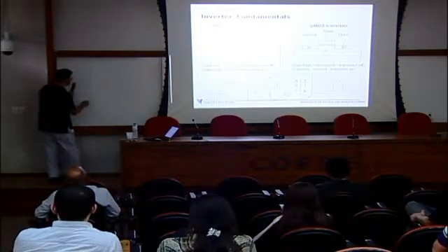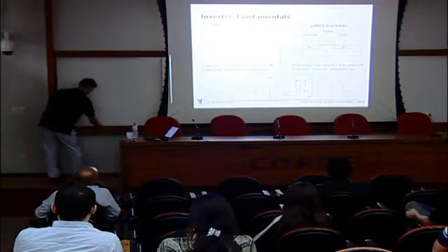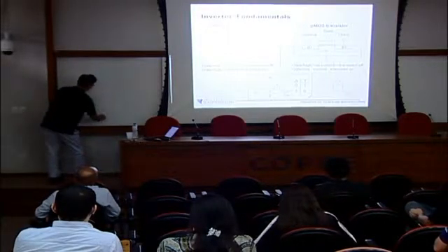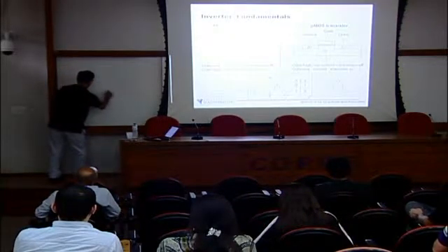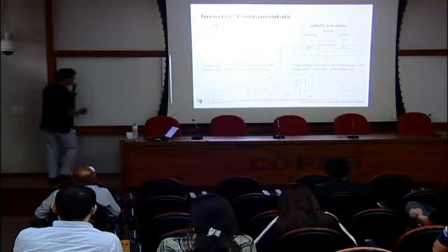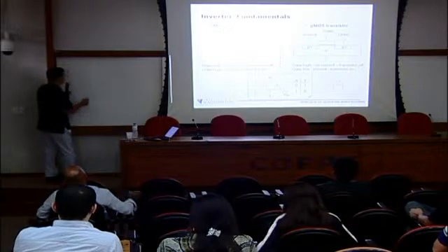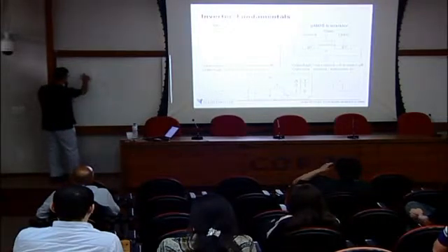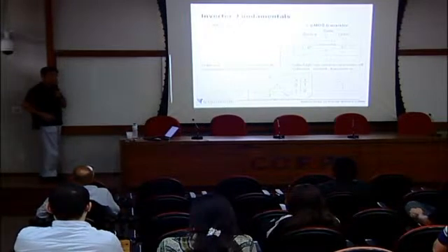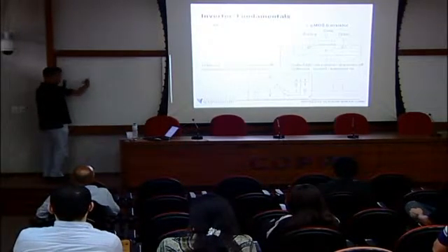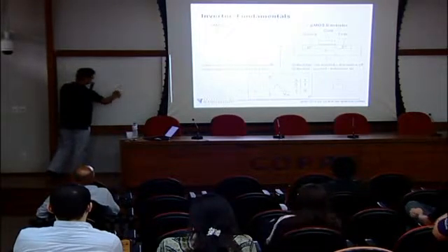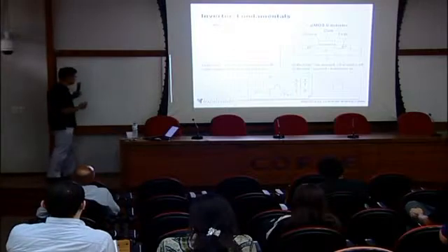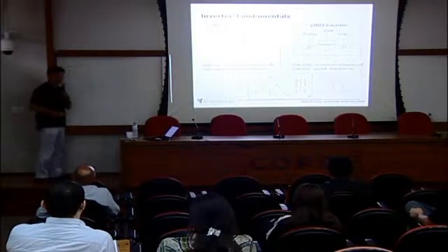Now we will apply one at the gate. So input is A and output is Y. Okay, Y is there, and we will apply a 0 to the gate. Then let's see what's happening. When we apply 0 out there, then there is no current for this NMOS transistor. Then this one is kind of terminated, turned off, and then only this one is on. Then this VDD is directly connected to this Y, right? Because the current is only on for this PMOS. Then the output is 1, right?